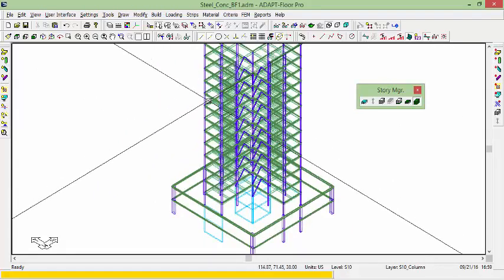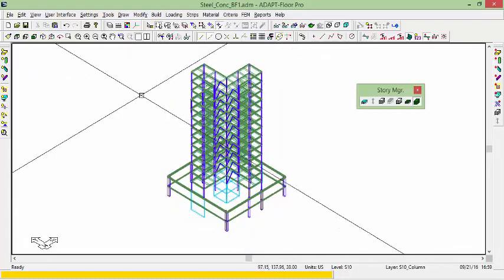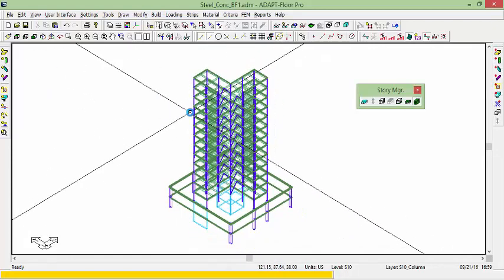The next step will be to apply loads. So we're only going to consider lateral load. Again, we simply want to show how to get the reactions into the structure, the concrete structure, and analyze at one podium level for the reactions being dumped onto it from the steel structure.